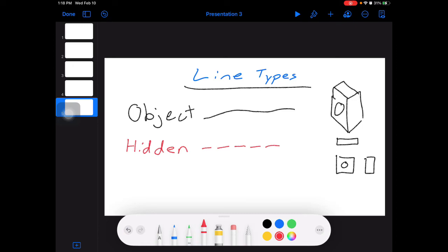So if I follow this left edge of that circle up into my top view, I'm just going to put some short dashes in there for the left edge of that circle. Do the same with the right edge, follow it up, and then in my drawing it's going to be a set of short dashes like that. I'm going to erase, I don't need those extension lines there. And I do the same in my right view. Going to need my top edge of that circle and the bottom edge of that circle. And there we go. We have our hidden lines. Hidden lines, again, something's behind that surface. You cannot see it, so we use a dashed line to represent it.